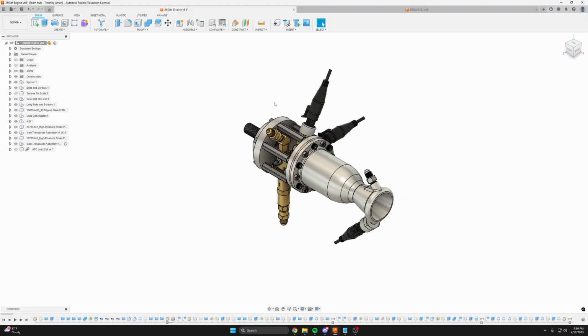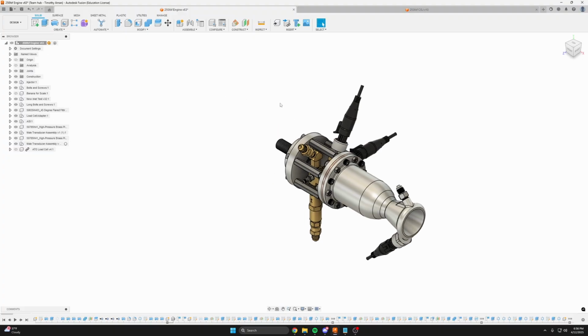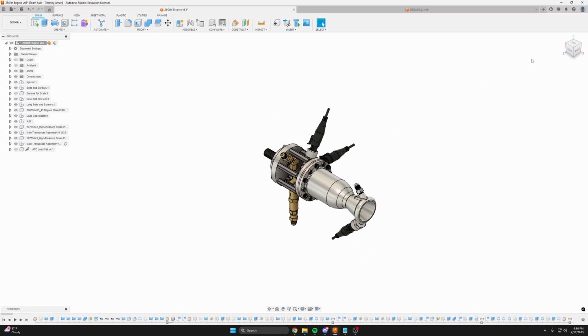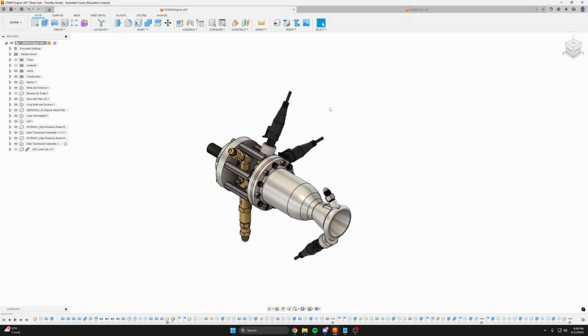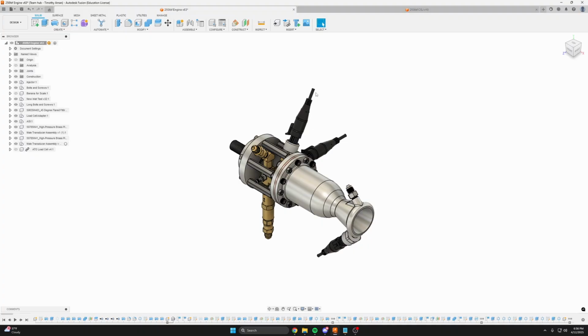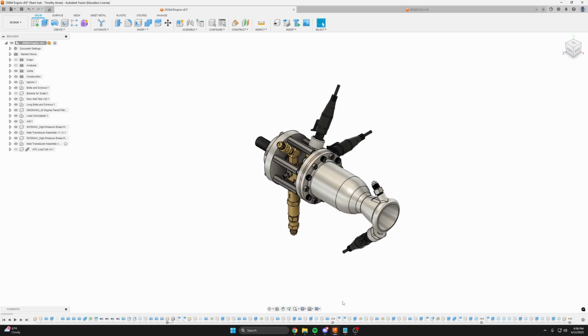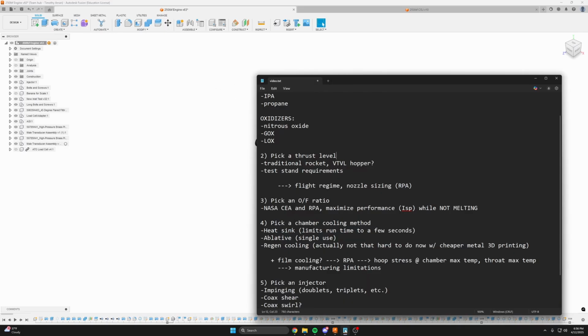So like we're using 1/4 inch sheet metal as sort of the plate that we thrust into. So 250 pound force is also kind of the maximum thrust that still gives us a nice factor of safety there. So the test stand also gated our decision to pick that thrust level as well.